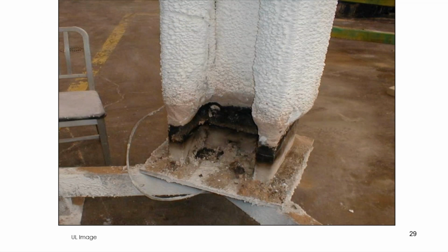So this is another way of looking at that same concept of the edge effects. Remember I mentioned the sand base that's used in the column furnace? The lower 4 or 5 inches of this test sample was buried in that bed of sand, so it didn't see much heat. If we look at the very bottom, we see the intumescent fire resistant material has really seen very little heat, and has not expanded at all.